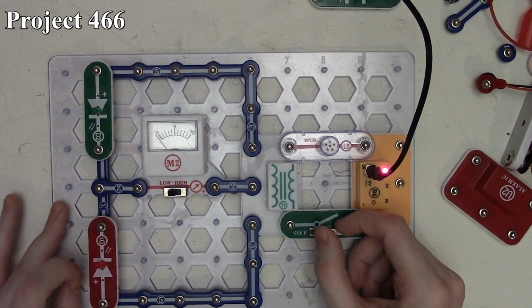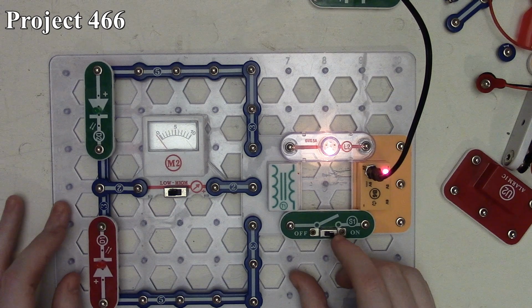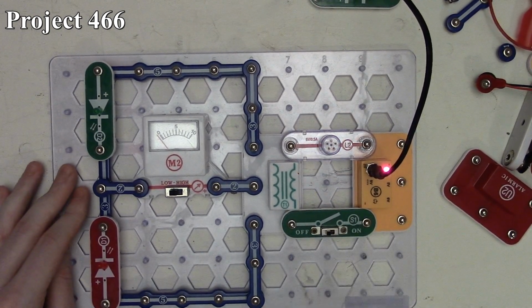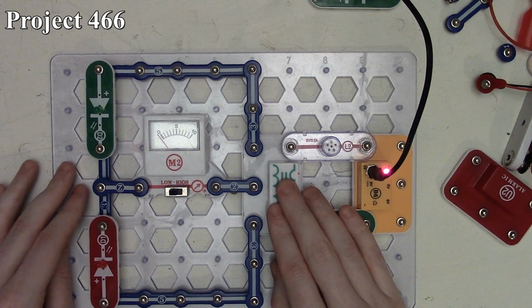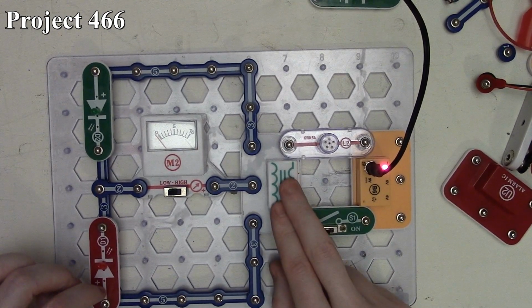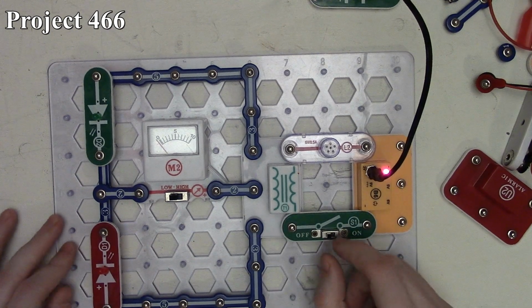So turn on the switch, watch our red LED. See our red LED briefly came up. You may have seen our meter deflect. Turn the switch off, watch our green LED. And our green LED blipped there, because when we charge up the transformer, our red LED lights momentarily when the field in the transformer collapses, which gives us our other waveform for alternating current. Then it momentarily powers our green LED.